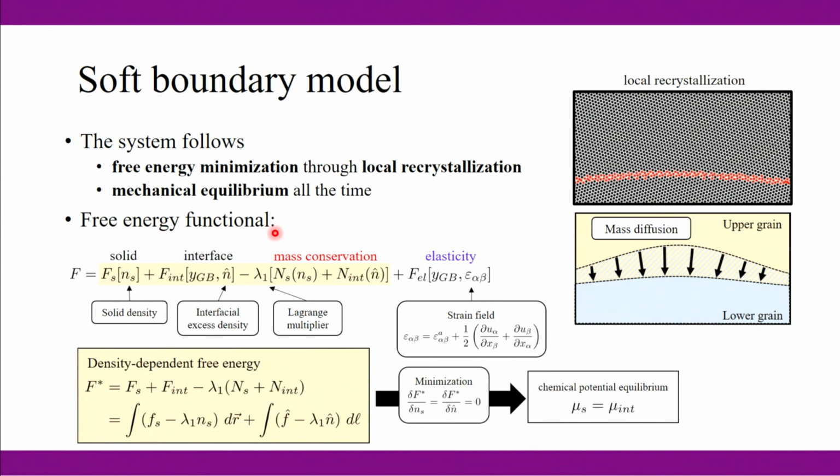One important ingredient we're putting here is that instead of just putting the surface energy gamma, we're actually also making the surface energy depend weakly on the y position. And it's going to be a periodic function along the y position, and the periodicity is associated with the coincidence site lattice, the dimension of that. All right, so if the boundary just goes along the y direction, once it goes across the coincidence site lattice periodicity, it's going to repeat itself. So this term actually helps us to capture that amplitude-dependent growth rate. All right, so that's important.